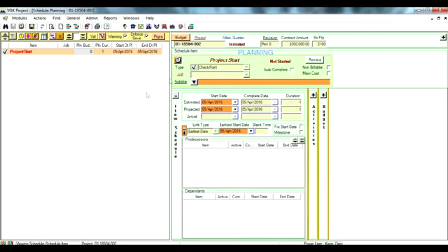Note that a new schedule is automatically linked to the chosen project. It has only one item, Project Start. This item was created automatically and it marks the beginning of the schedule. To compile your schedule, you simply need to add your items and their information. So to add an item to the schedule, just use the toolbar button, Add New Item to the same level.